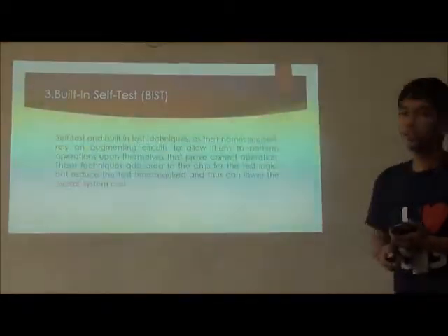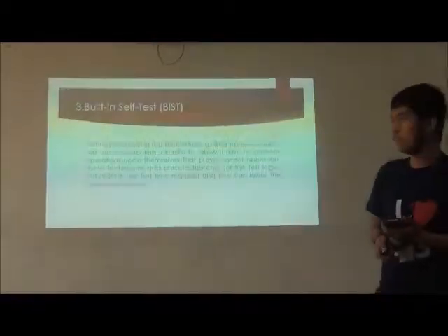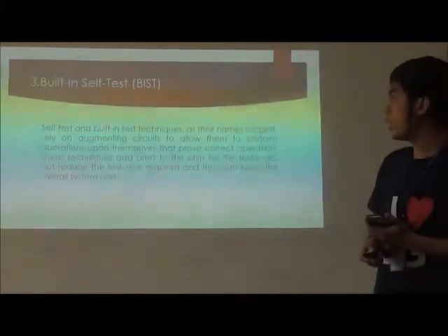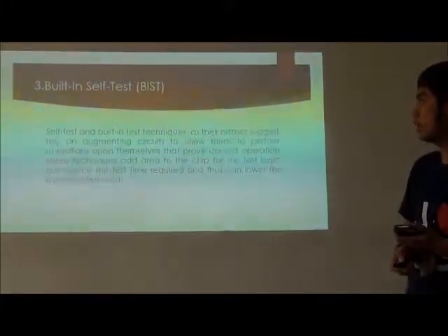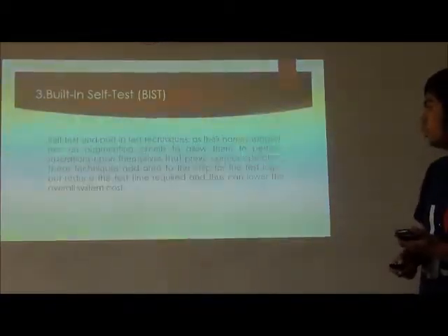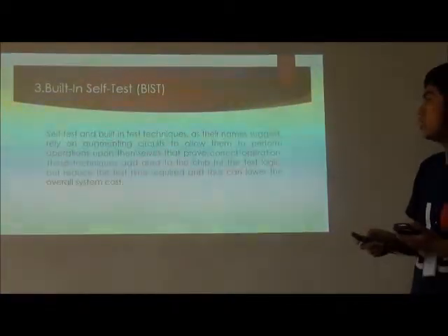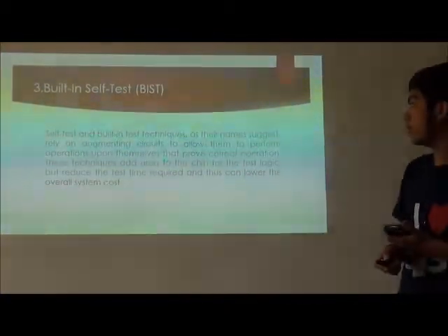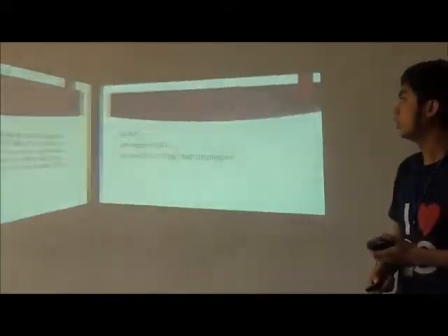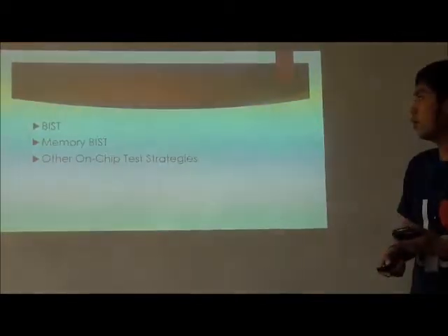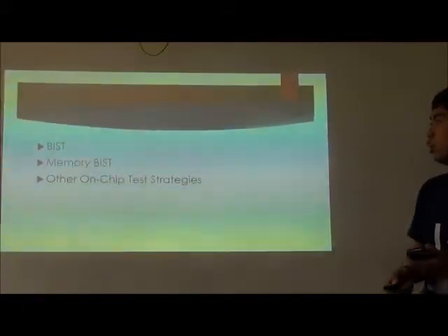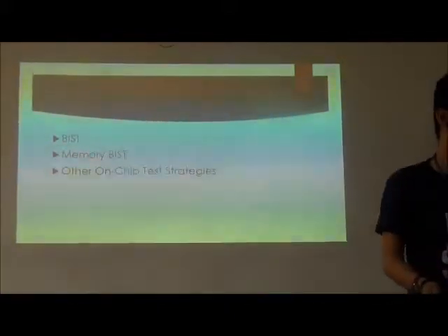The third is built-in self-test, or BIST. Self-test and built-in test techniques, as their name suggests, rely on augmented circuits to allow them to perform operations upon themselves to prove correct operation. These techniques add area to the chip for the test logic but reduce the test time required and lower the overall system cost. Under BIST, we have BIST itself, memory BIST, and the last one, other on-chip test strategies.